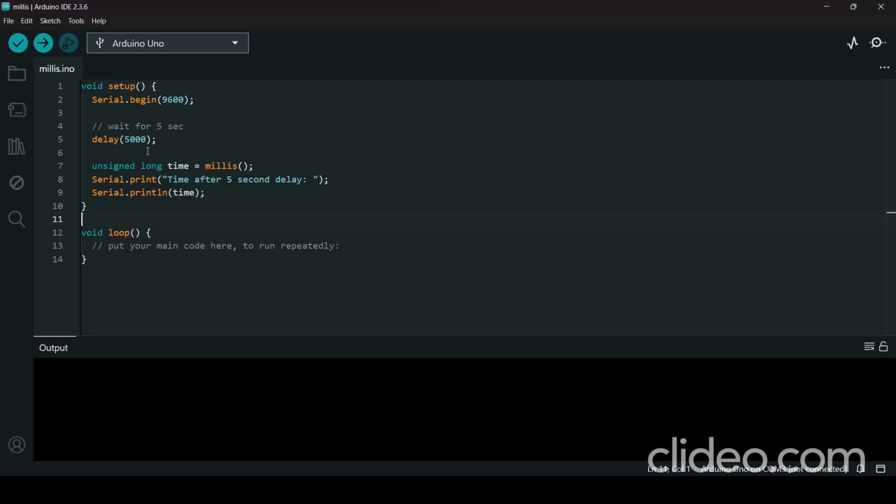If your answer is 5000, then comment down below because you are partially correct. Because sometimes this code returns 4999, sometimes 5000, and even sometimes 5001 and 5002. Right? So why is this so? Actually, there is no problem in the Arduino board, but the reason is something different. So in this video, I'm going to explain the meaning of this millis function which we are using in this code and how it works, right?